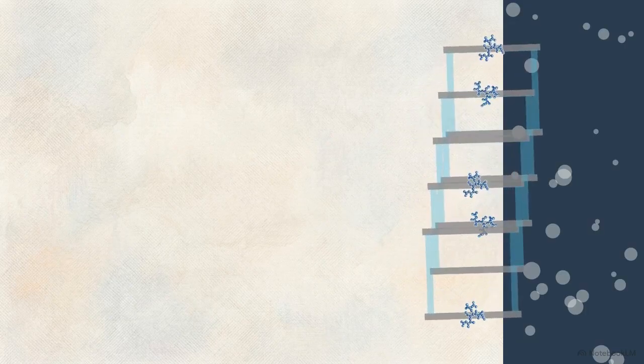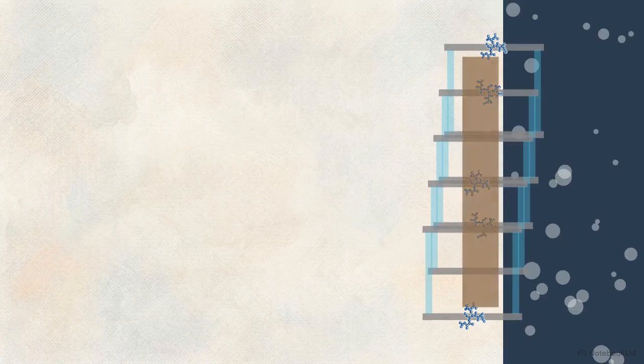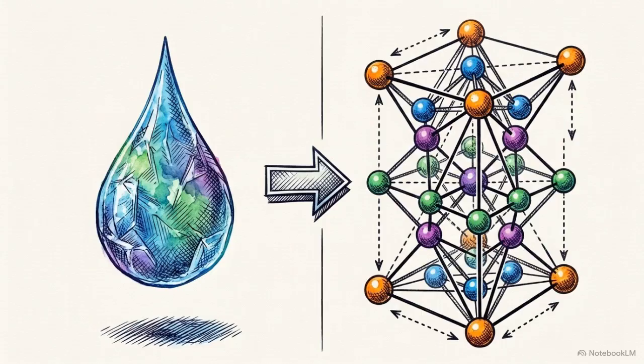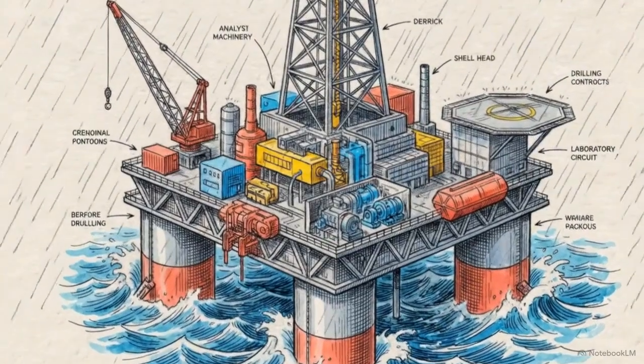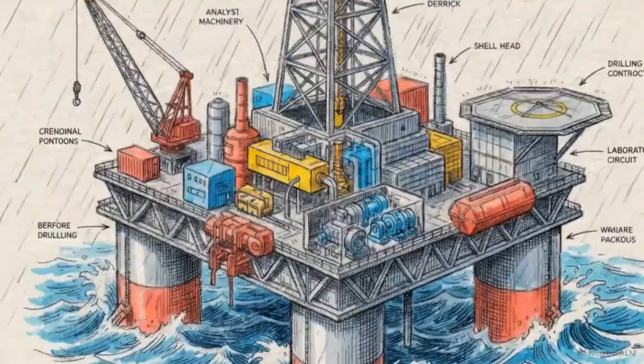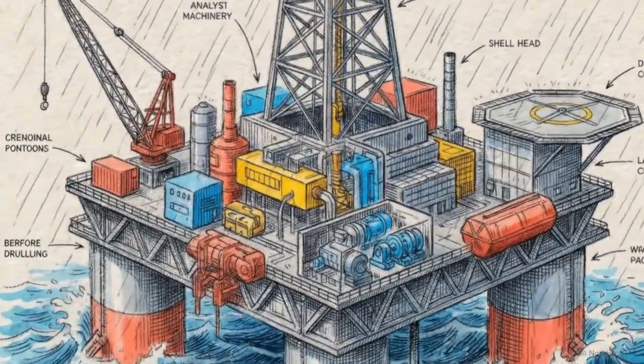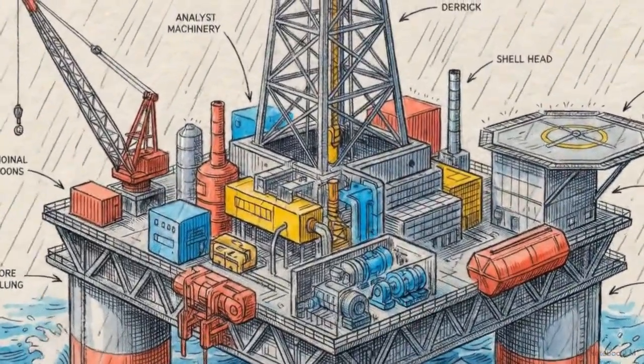However, because the plates remain dispersed rather than aggregated, they continue to lay down a tight, impermeable filter cake against the wellbore wall. This injection physically alters the fluid's structural matrix at the atomic level, restoring flow by dismantling the electrical bonds of the brush heap. A master mud engineer commands macroscopic industrial forces precisely because they understand the microscopic geometry of the atomic lattice.